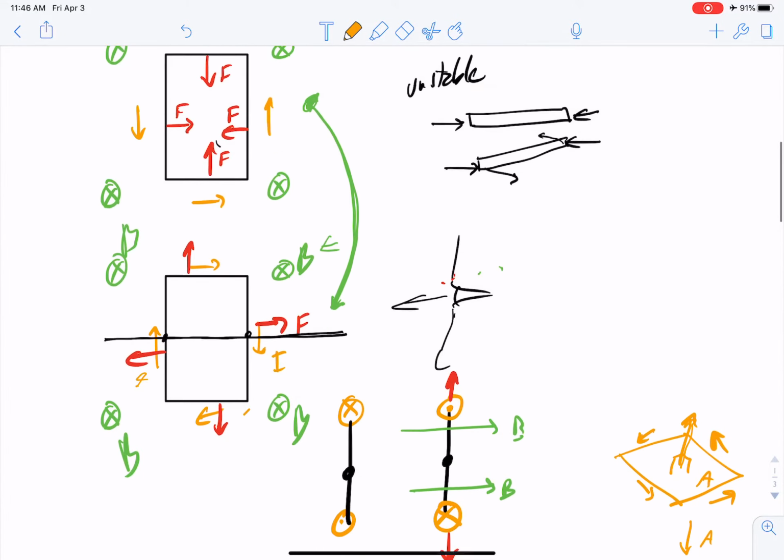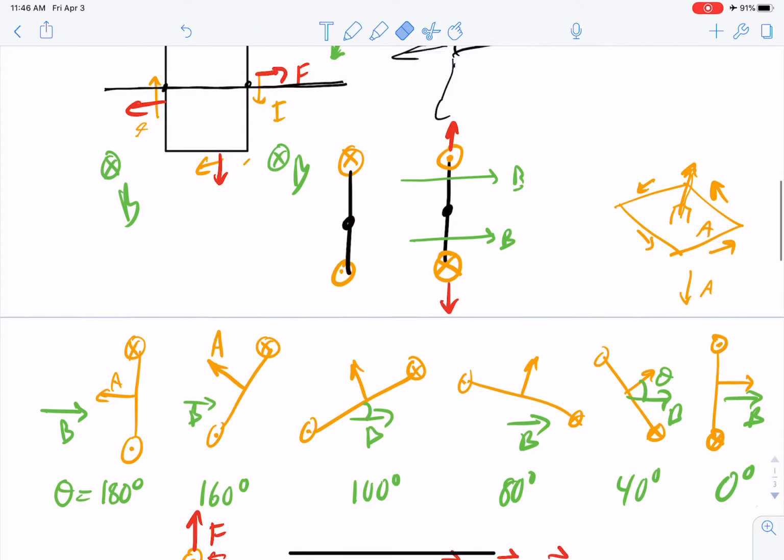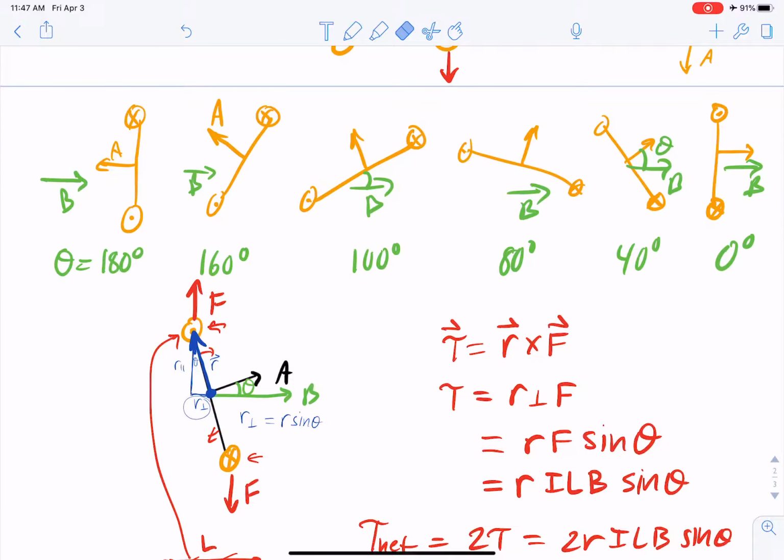If we look at it up here, you see that also. Here are the currents. On this top one, current's going counterclockwise. Here it's going clockwise. So in any motor, what you have to do is essentially once it's reached this position where it's happy, you have to flip the direction of the current. And they all do it by different means.